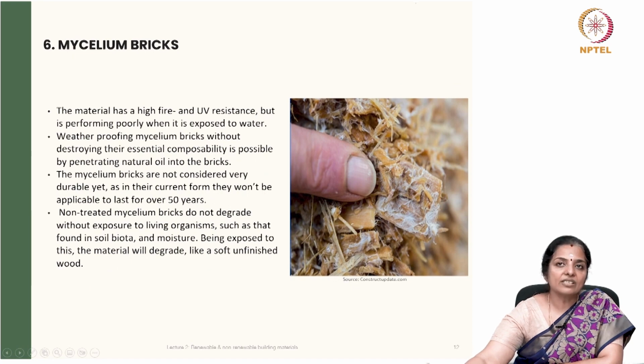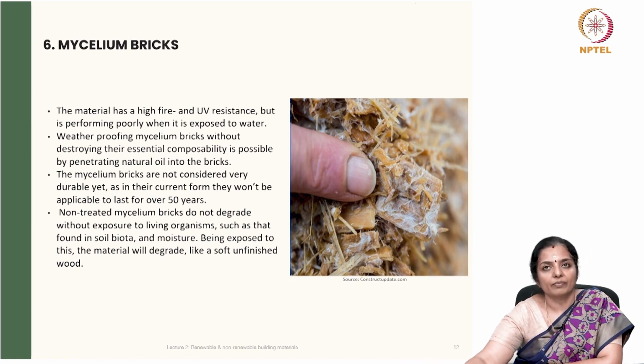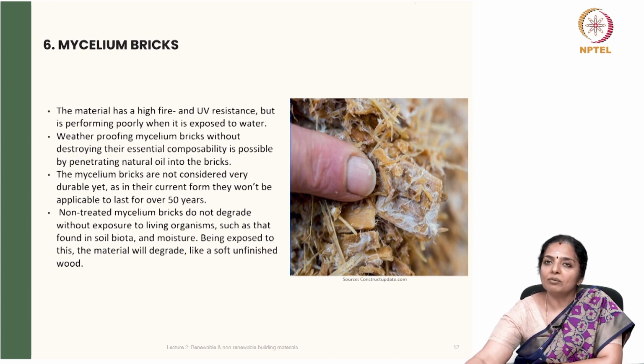The material has very high fire and UV resistance, but is performing poorly when it is exposed to water. Weatherproofing mycelium bricks without destroying their essential compostability is possible by penetrating natural oil into the bricks. The mycelium bricks are not considered very durable yet, as in their current form they won't be applicable to last for over 50 years.